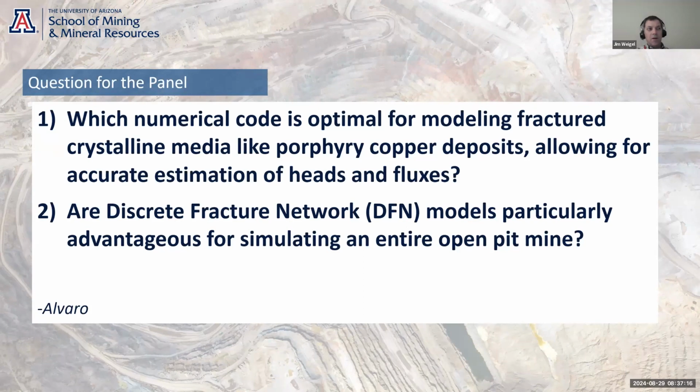Do you need to go in and do investigative drilling to try and figure out why those heads are lining up that way? You might find that there's an unmapped fault, because I don't know about you guys out in the fields and at other sites, but we seem to always find new faults whenever there's a new instability. The conceptual model is constantly changing.